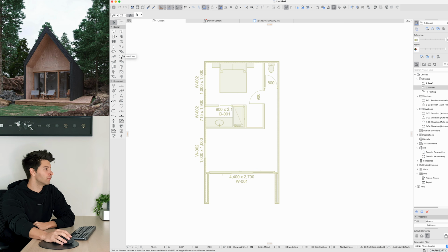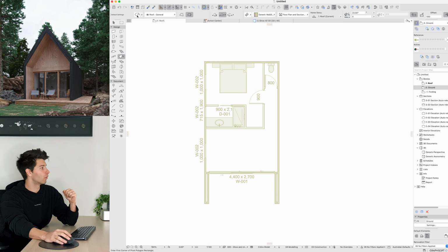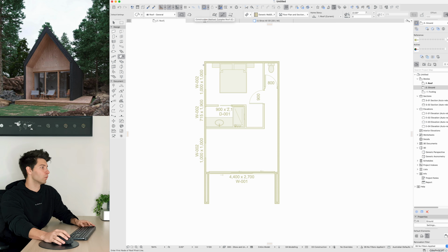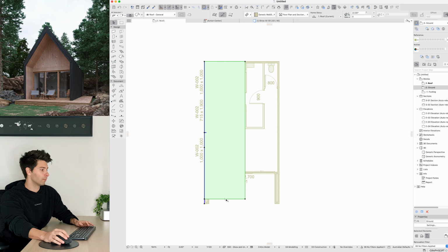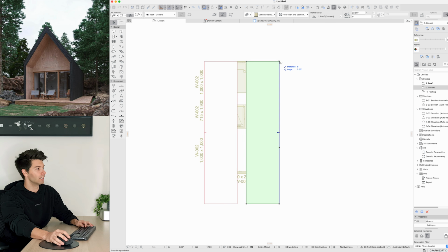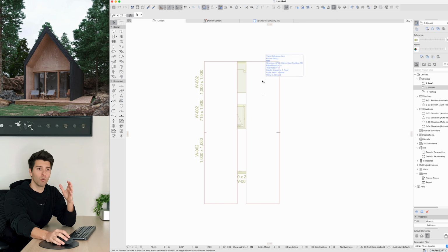Now to create a simple roof structure, let's go to our roof tool here on the right. We want to select a very simple roof style. We don't want to create a multifaceted hip and valley roof. So we just want to create one simple roof. The pitching point will be from the outside leaf in this scenario. And then we can go ahead, drag, drop, click, extend to where we need, Control or Command M to mirror, hold the Option or Alt button, adjust this secondary roof in line with the outside wall below.